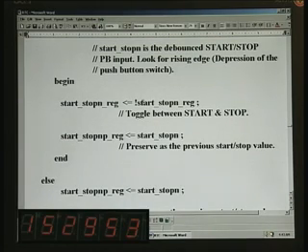So what you need is an inversion, and that is precisely what this statement is for. The same signal is inverted and assigned to itself. In other words, it is toggling between start and stop. This is how you achieve it with a single button rather than having to use 2 different buttons. And another thing is this previous value, you should not forget to load it with the present value, and this is an important thing. If you miss this one, it will not work, okay.